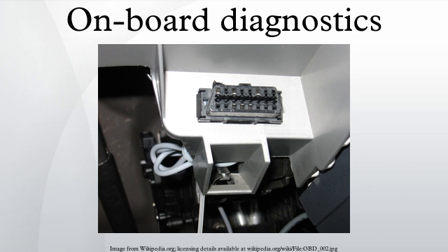Professional handheld scan tools may possess more advanced functions, access more advanced diagnostics, set manufacturer or vehicle-specific ECU parameters, access and control other control units, such as airbag or ABS, and offer real-time monitoring or graphing of engine parameters to facilitate diagnosis or tuning. Mobile device-based tools and analysis. Mobile device applications allow mobile devices such as cell phones and tablets to display and manipulate the OBD-II data accessed via USB adapter cables or Bluetooth adapters plugged into the car's OBD2 connector.